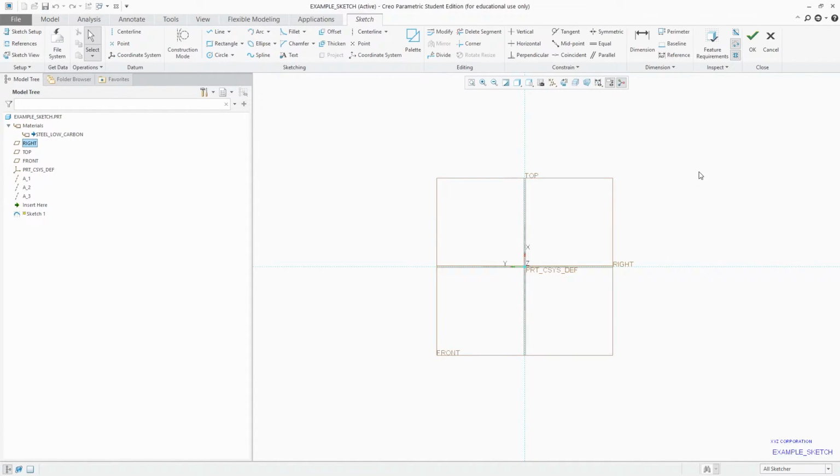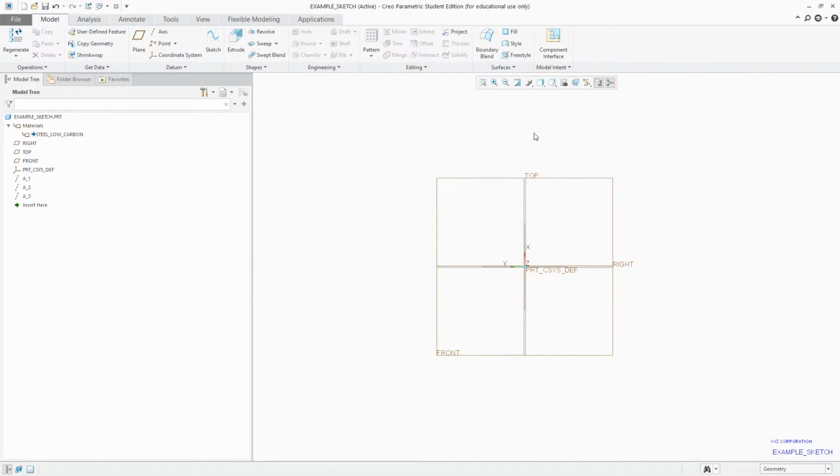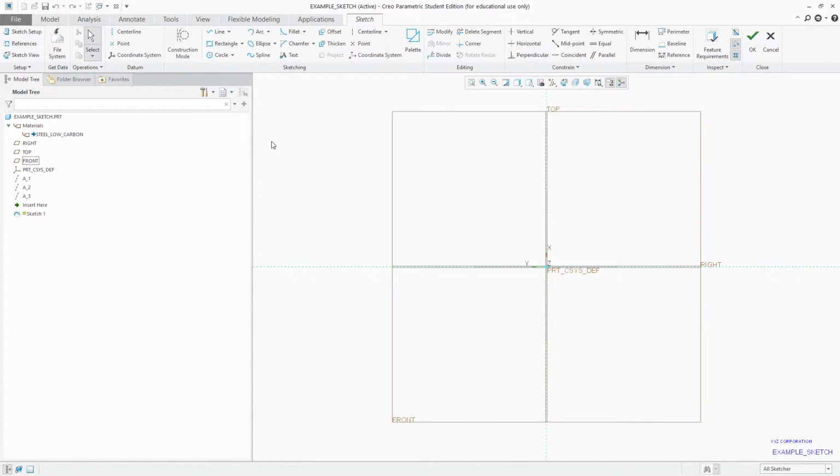Now we will click on sketch. Again, I just want to show you how easy it is, because I wanted to explain how you can customize it, and I want to again show you my most preferred way to do it. And you can also use it if you like. Just select plane and press S. It is as simple, just 1 second. Also you can speed up your process by disabling the animation, because animation also takes some time.